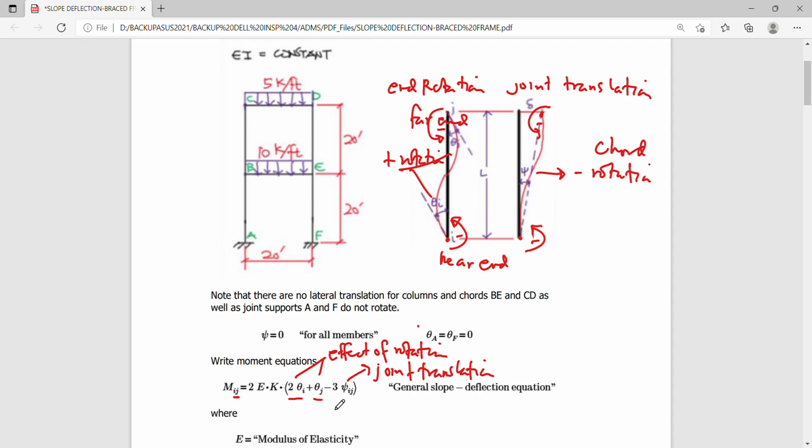So the 6 here simply refers to the derived equation considering a delta deformation, wherein your moment due to that displacement is simply equal to 6EI over L squared times your delta, where your 6EI here represents the 6 times 2 here.